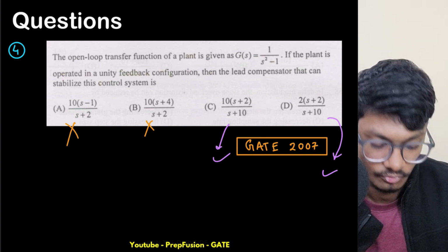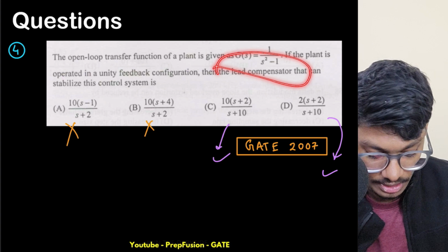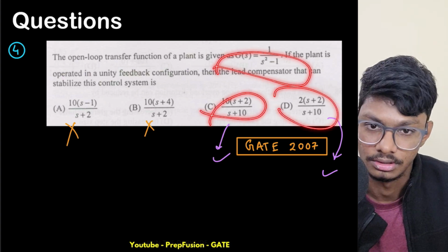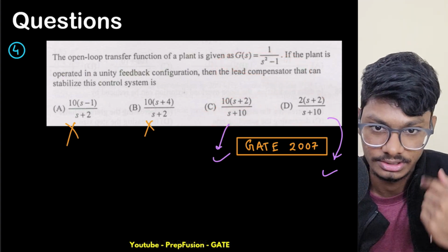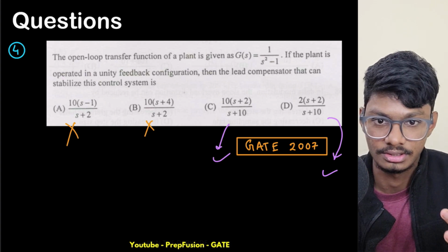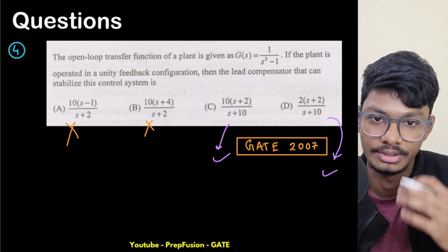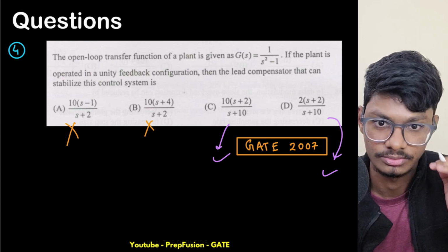For this, what you can do is check, because this is a second order system, and if I multiply these things, the order will increase by 1, so it will become a third order system. So we can use the Routh array trick for checking the stability, that is the internal product should be greater than the external product for my system to be stable.